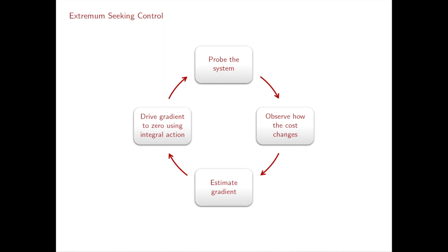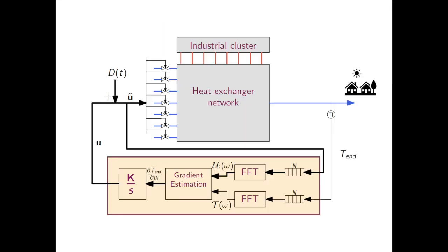We therefore consider a model-free method where the heat recovery is maximized using only a single temperature measurement measured at the end of the heat recovery network. This avoids the need for temperature measurements from the different heat sources. The model-free nature also implies that the proposed method is not susceptible to plant-model mismatch and thus can be used irrespective of the type of heat exchanger, the number of heat exchangers in each split stream, heat exchanger fouling, etc.